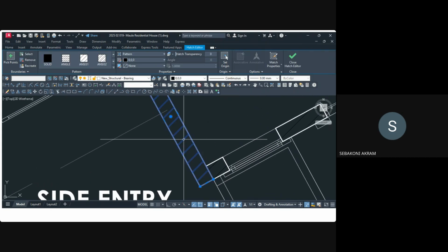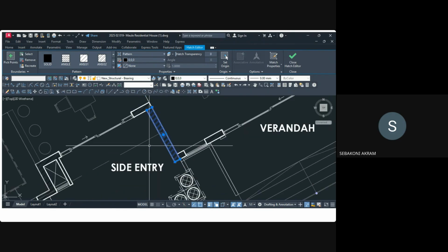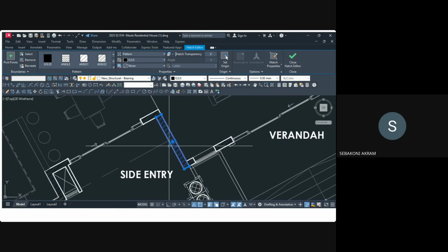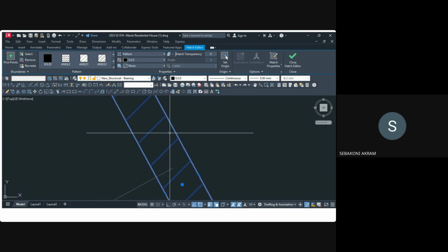You see this hatch I've selected? It is a solid one, not one of lines. In electrical drawings, when you leave those solid hatches that are from the architecture drawings, they make our work look okay, but after you print out the work, the hatch would be more seen. This one is fine, it is a line hatch.